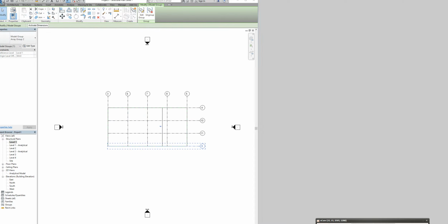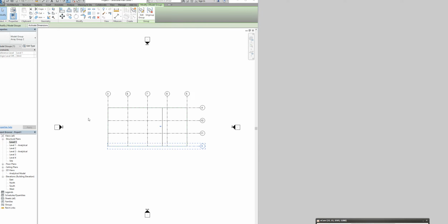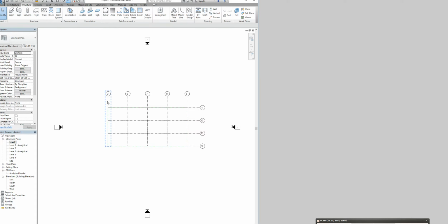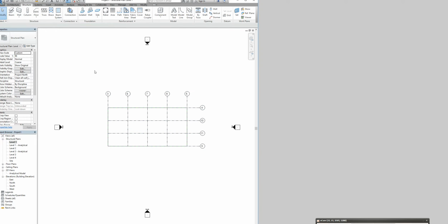Next slide. Select vertical grids and ungroup. So I select all the vertical grids. Sorry, I just moved this. I lost my drawing. Okay. So all the vertical grids and ungroup. Same with these ones. And ungroup. Best way to see if something is ungrouped, if the group is dissolved, is just select all the grids, so it should be fine.